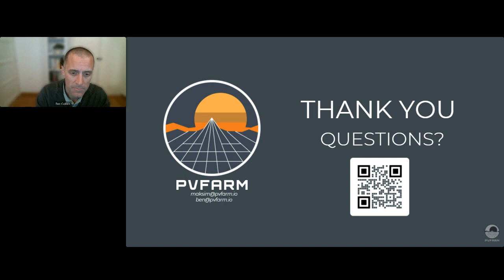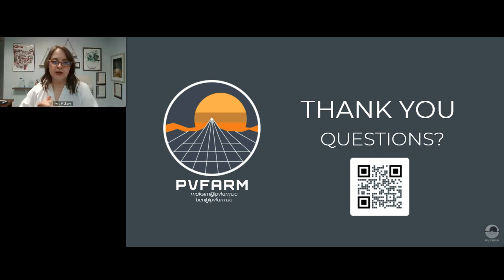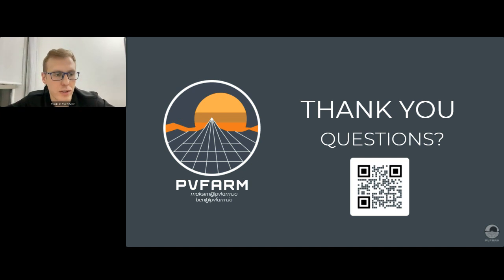Perfect. Someone is wondering, can you change the tracker tolerance and determine the amount of cut fill required according to the slope or elevation tolerance? Take that, Max? Okay. Yeah, I'll take this one. Yes, we can change the tracker tolerance, and we can define the net gradient balance for a specific site or for a specific area. So we cannot specify it for every tracker, but we can specify it for a group of trackers or a specific area. Okay. Good question. It's up to you. Yeah, the short answer.